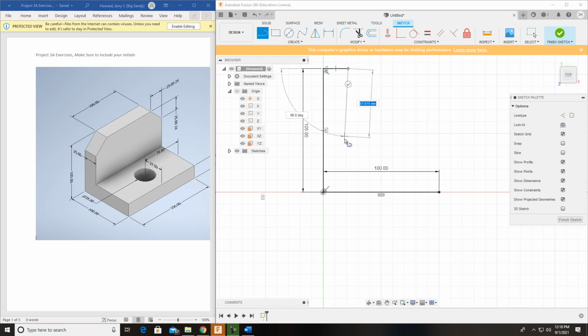You can actually just draw it up. This is what parametric modeling is. You can just draw it up, you know. You can draw it up and see how it's enclosed. It kind of turned like a blue highlight, and that's what you want. You want it enclosed so you can extrude it. You can add that feature mode and put that depth to it. But I know that dimension up here wasn't right. All you have to do is come up here, dimension, click on it, and then just click again, change that to 25. The dimension was already up, type in 25.